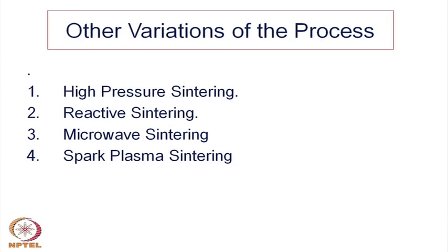We have just discussed two different techniques, two most important techniques which normally occur in different materials. One is solid state sintering, the other is liquid phase sintering in presence of a liquid. Of course, there are different variations in addition of the liquid phase sintering also. We may discuss later on what are those variations, what kind of liquid it is, is it a reactive liquid, is it not so reactive liquid, and so on.